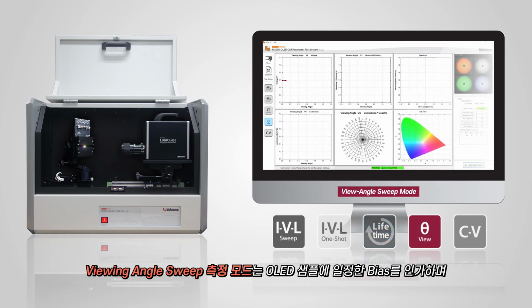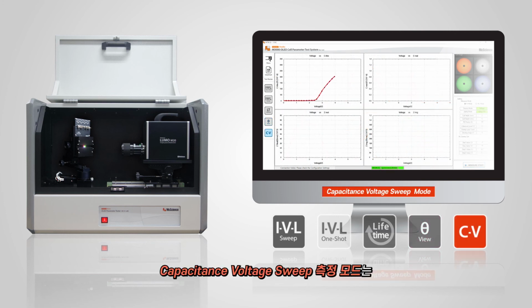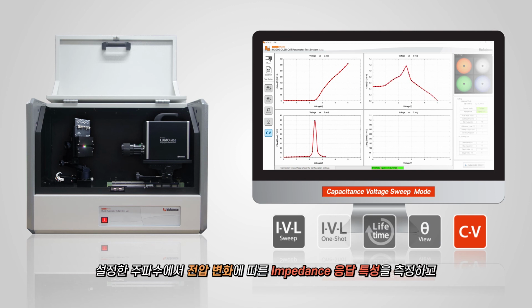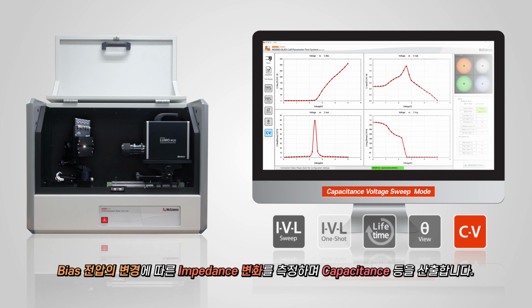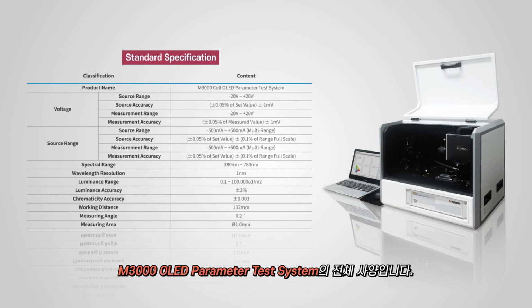Viewing angle sweep measurement mode also applies constant bias source to the sample under test, and measures luminance change following the viewing angle sweep. Capacitance voltage sweep measurement mode measures the impedance response characteristics according to voltage change at the set frequency, and the impedance change according to changes in bias voltage, and calculates capacitance. This is the full specification of the M3000 OLED parameter test system.